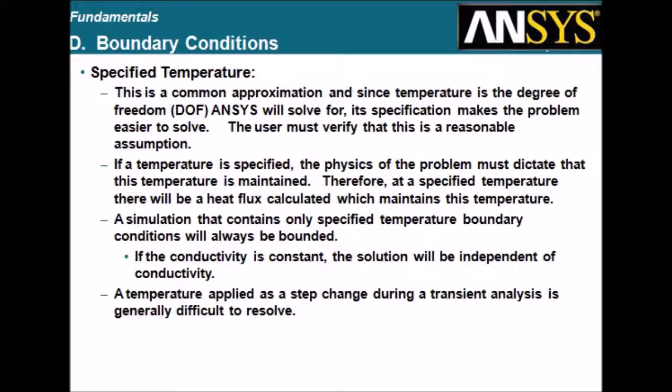A simulation that contains only specified temperature boundary conditions will always be bounded. If the conductivity is constant, the solution will be independent of conductivity. A temperature applied as a step change during a transient analysis is generally difficult to resolve.